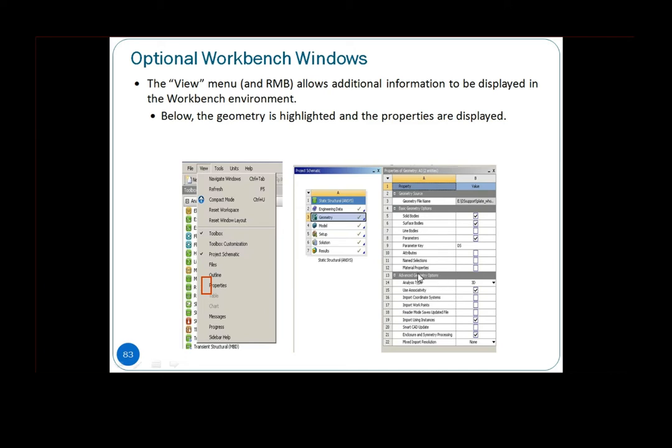Then analysis type, this is under geometry. Analysis type can be 3D, 2D, or whatever. If you are looking into 2D, then for the three-dimensional element types, you will see you have no choice or selection options later on. So that is the property where you can make further additional settings.